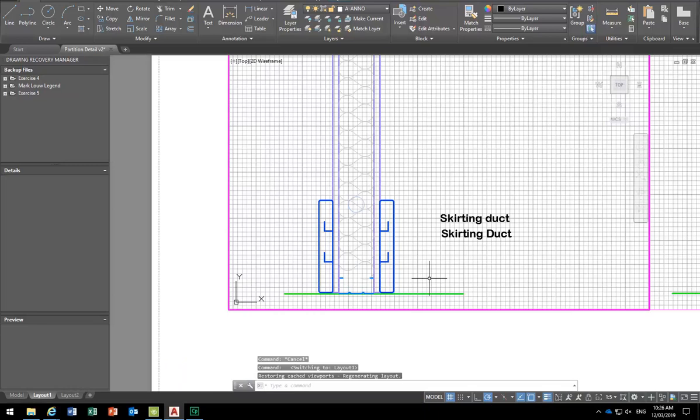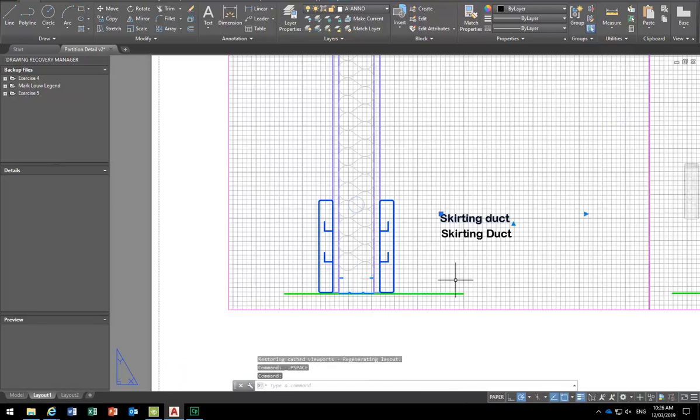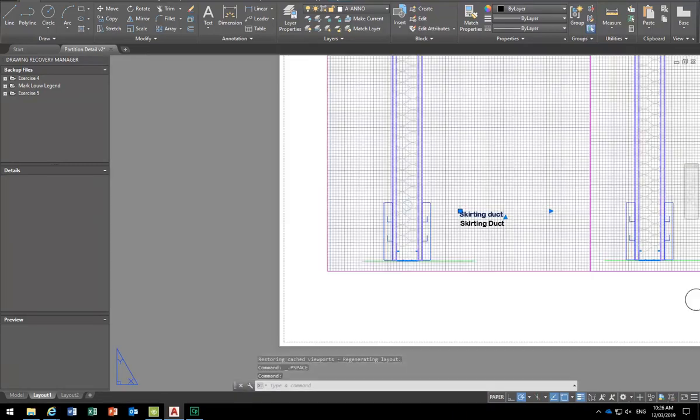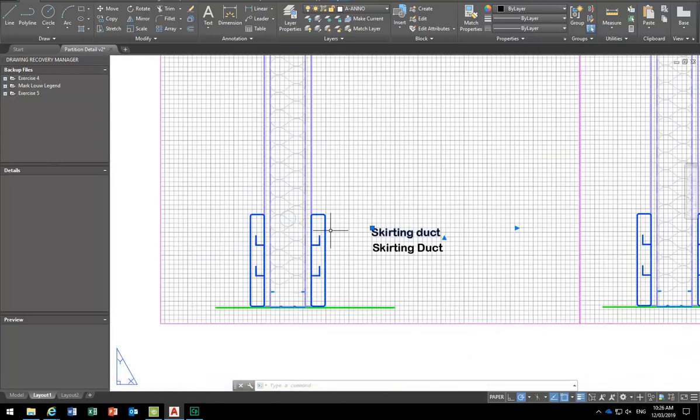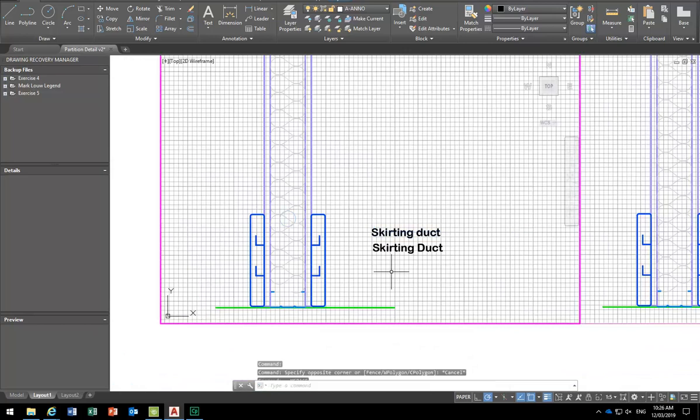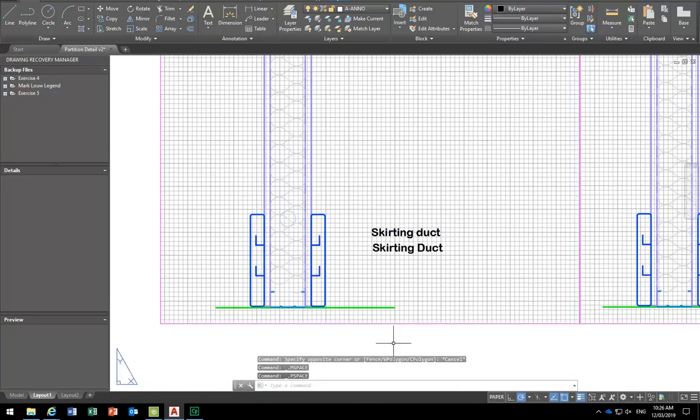So you can do it here like I've done it in paper space, like this one here. And that can also be easier because if you want to copy from one viewport to another, that can be easier. So you've got a choice. It doesn't really matter how you do it, as long as you're using that annotative option, you can do it either way because it'll detect the scale.